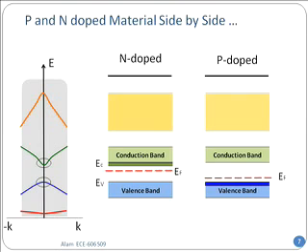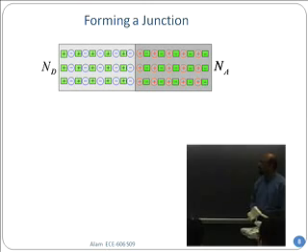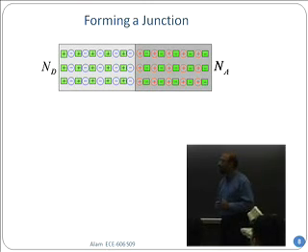Rather, you need to diffuse things in so the junction doesn't have too many defects. That's what we did, right? Diffuse atoms in, and therefore the junction doesn't have too much defect. Only then, interesting things will happen, as we'll see. Assume, therefore, that this is a diffused junction. The junction has been created and there are no surface defects. Then in that case, what will happen?